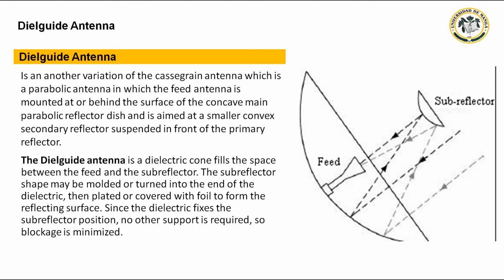The feed illumination travels inside the dielectric, and potential spillover is reflected back to the subreflector if the cone angle is less than the critical angle for total internal reflection. For a good dielectric, a feed Fp over dP greater than 0.7 satisfies this condition, where Fp is equal to the parabolic dish focal length and dP is equal to the parabolic dish diameter.